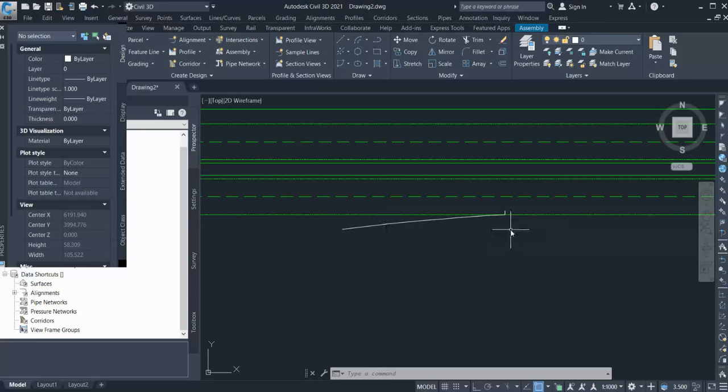and that nose area should be, there are two values for that. Either you go with the 70 or 80 meter area, or you should go up to where you get a 1.1 to 2 meter gap between those two hard shoulders for the main line or the loop. The 70 or 80 meter I said is based on the main line design, so you have to check your country standard, that for 100 kmph what would be that nose area length. So you need to check that.